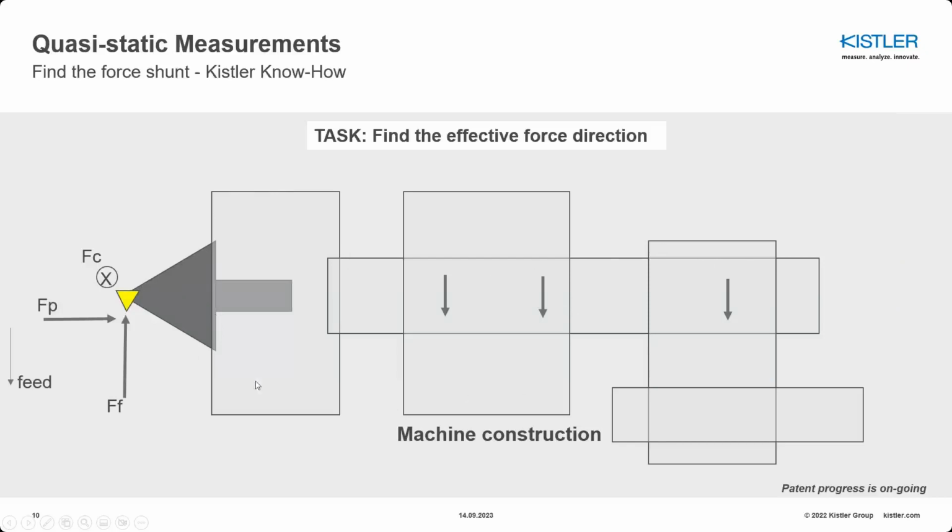So you have some constructions. Now, the task is really being able to install the sensor at certain positions so that you are as close as possible to the cutting point, but still not interfering with the manufacturing execution and movements, and to capture the tool wear.